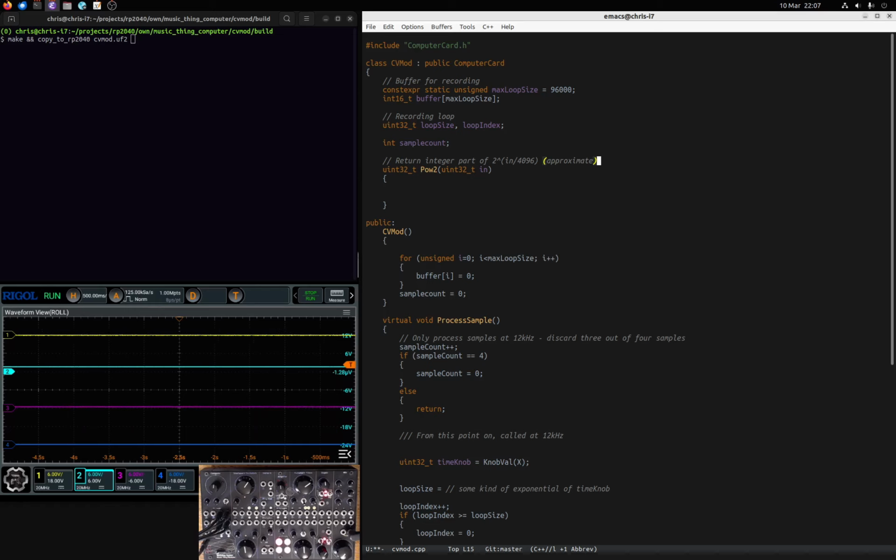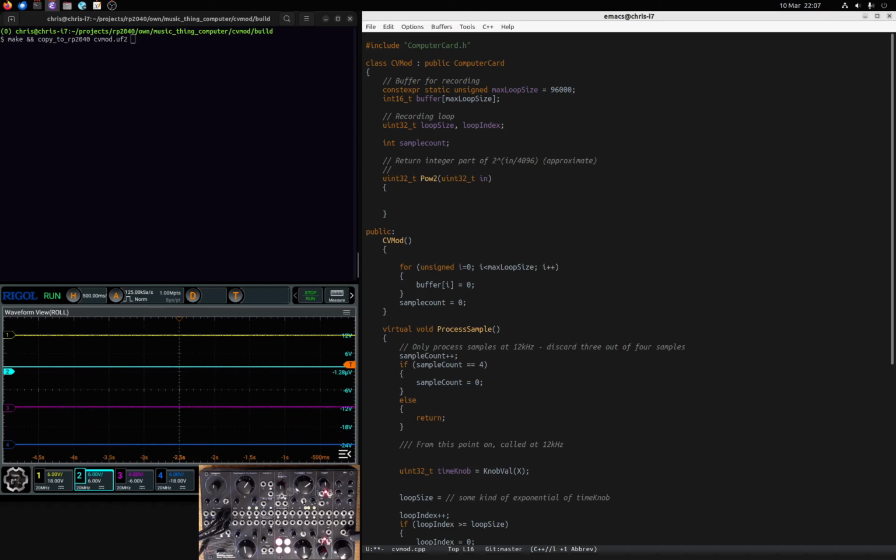And so for those 4096 steps, what we're going to have is a 7-bit lookup table that is 128 entries, which is not too many, with 5 bits, that is 32-step linear interpolation between steps.